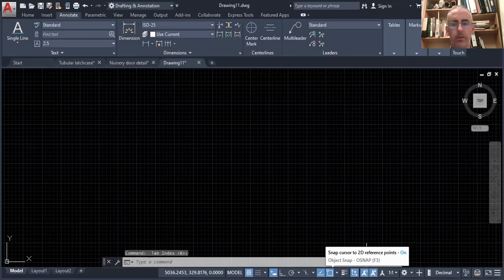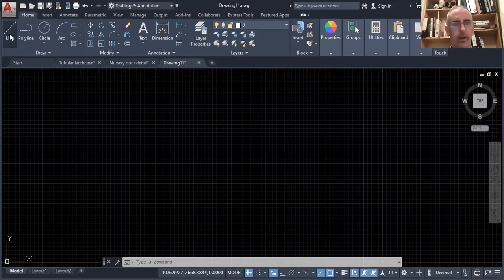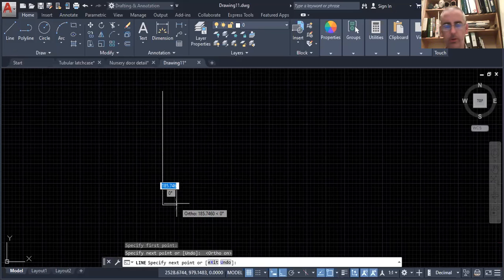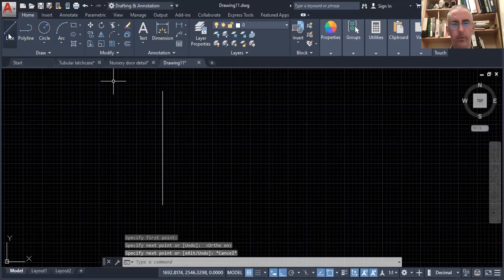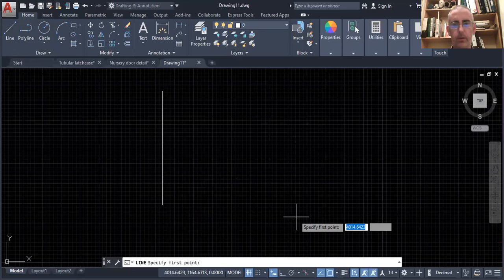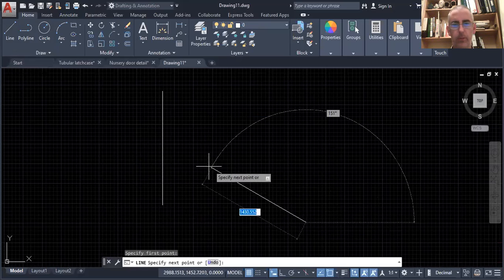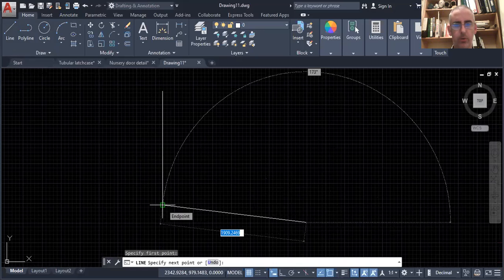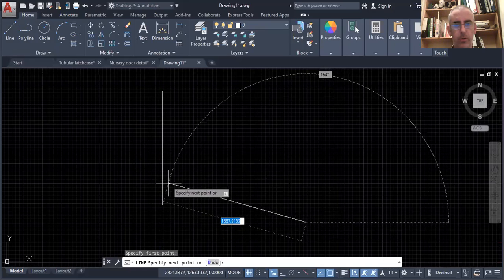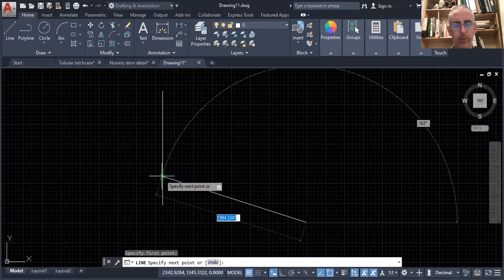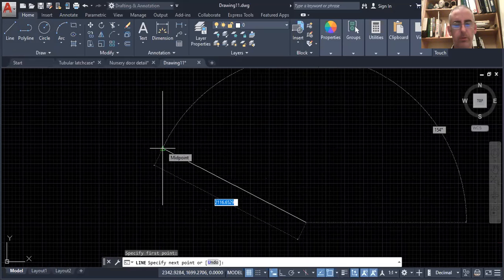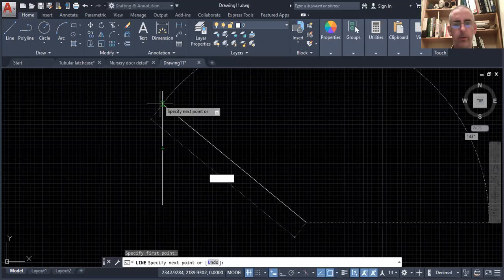We're going to keep that highlighted just now, and now I'm going to just draw a line down halfway down the screen there, and then escape from that. Now I'm going to put my ortho mode off. So the good thing about your object snaps is you can snap on to the end point of a line, and that brings up a green square. You could snap on to the nearest point on a line, which is a little bit more random, or you could snap on to the midpoint of a line, which is a green triangle, or the other end point of